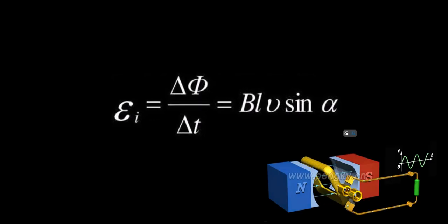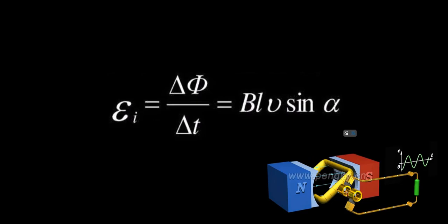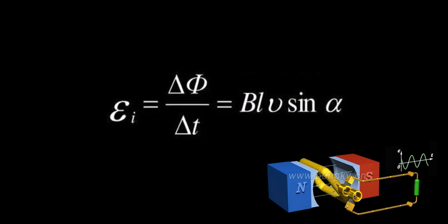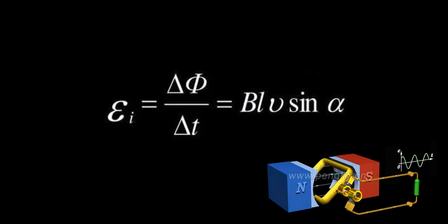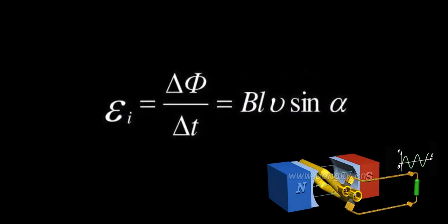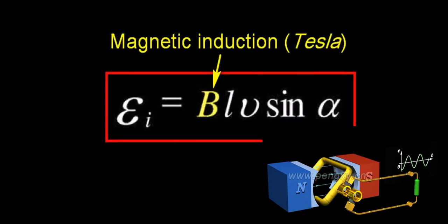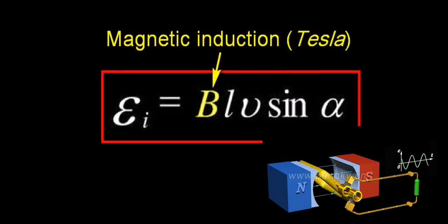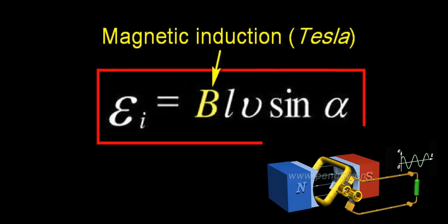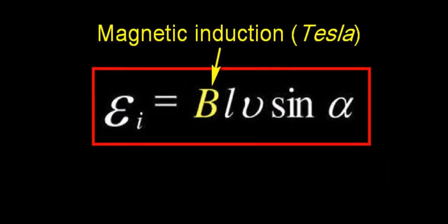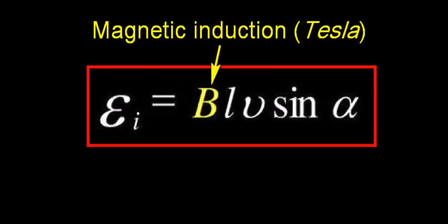For a conductor moving in a magnetic field, the formula for calculating EMF is used, which is the product of the length of the conductor under the action of magnetic induction, by the corresponding speed of the conductor, multiplied by the coefficient of the angle at which the magnetic induction vector is directed to the conductor. To fulfill this expression, an important condition is the magnitude of magnetic induction at the point of contact with the conductor. Let us remember this important point.